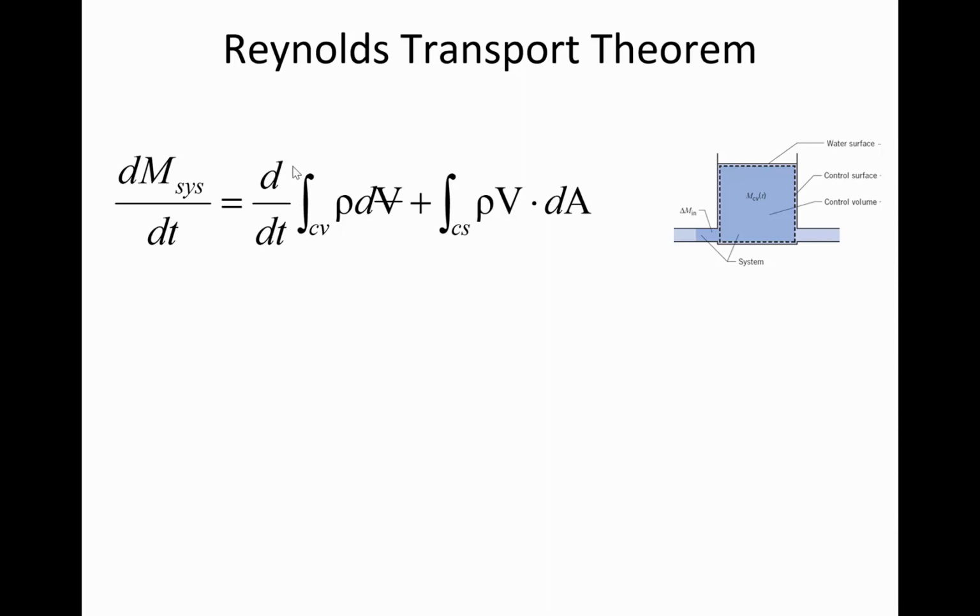And so this d/dt is saying inside of the control volume we want to see how the volume of fluid is changing. And here I want to just point out that the V with the strike through the center is to differentiate volume from velocity. So in the control surfaces, the V in that variable means the velocity of the flow through the pipes that are going in and out of the control volume, whereas the V here, we're talking about the change in volume that occurs when there's a net imbalance between the inflow and the outflow.